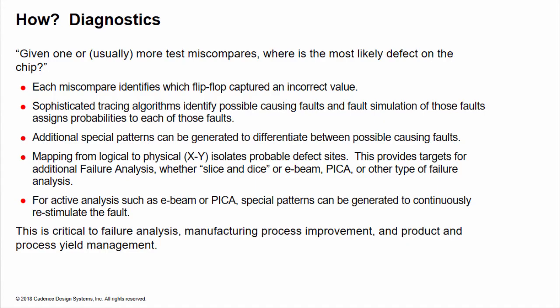If analysis tools such as electron beam or picosecond imaging circuit analysis are to be used, the test generator will create a small set of patterns that will continuously re-stimulate the suspected fault in a tight loop. This will allow these tools to build up an image of the behavior over many repetitions.